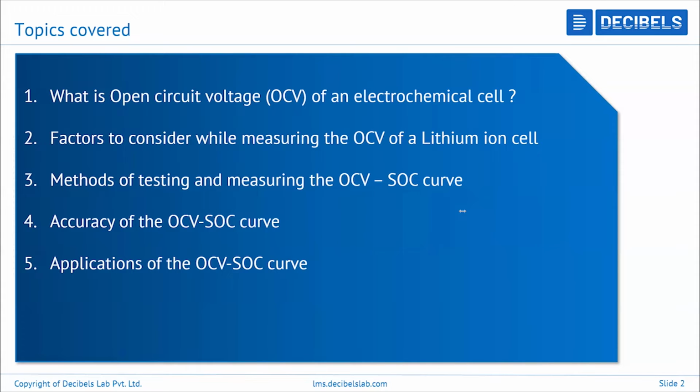Yeah, so we can just have a quick discussion on what are the possible answers, and then slowly as we proceed through the webinar, we can understand what are the implications of each question that has been put across here. So what is the correct definition of OCV, open circuit voltage of a lithium-ion cell? So there are two answers which may look possible to this. One is that it is the voltage of the cell measured immediately after the load is disconnected. And I see that around 37% of the people have answered that. And there is also another answer. It is the voltage of a cell measured when it achieves near steady state condition after the load is removed. And I see that 45% have answered that.